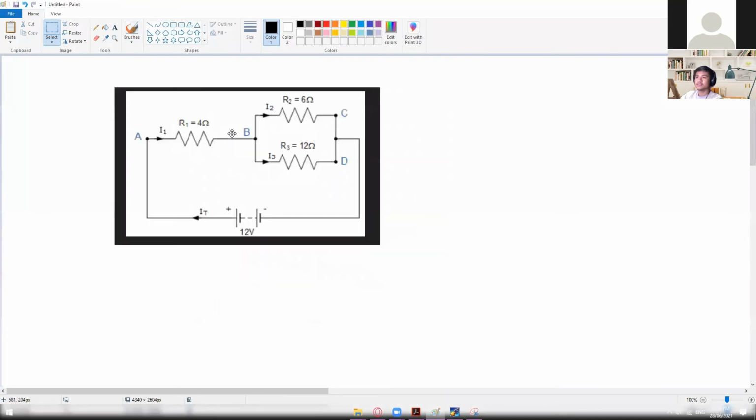Okay, so in applying a KCL, that's super simple. We can actually find the KCL equation right here, since we have one current entering and then two leaving. Just find the node wherein there is a current that is entering and then currents that are leaving at the same time. That's the way for you to know where to start doing your KCL equation.